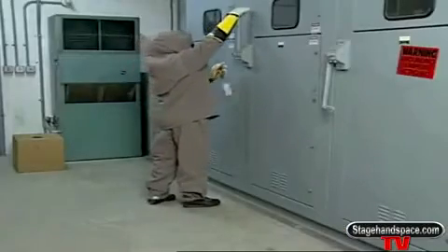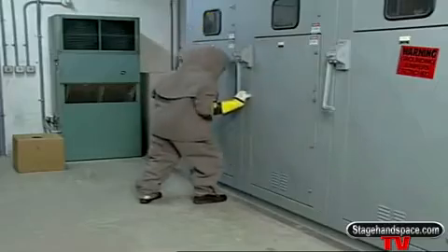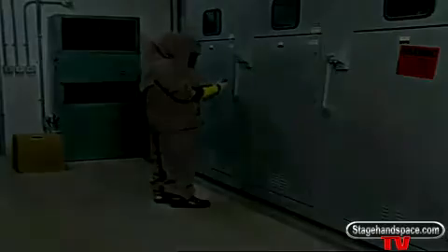Load-rated switches and circuit breakers or other devices specifically designed as disconnecting means should be used for opening, reversing, or closing of circuits under load conditions.